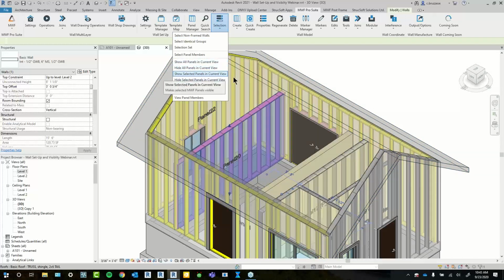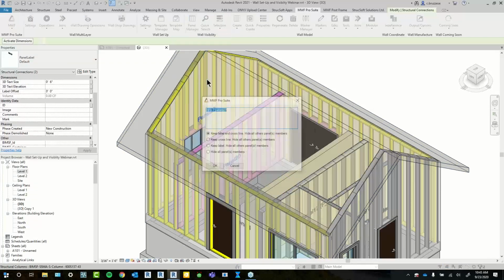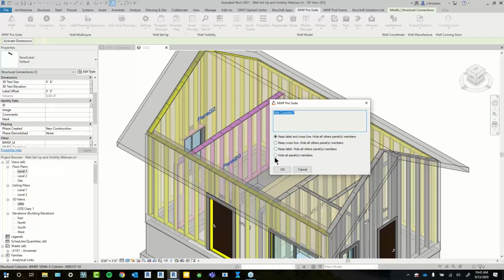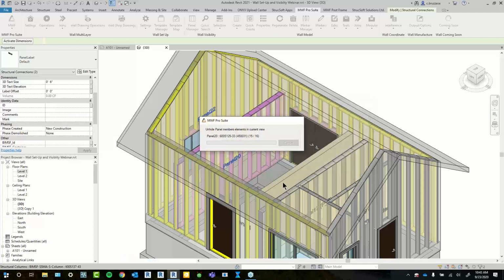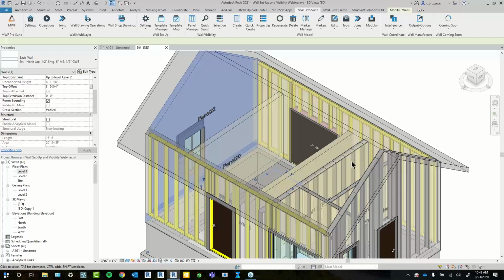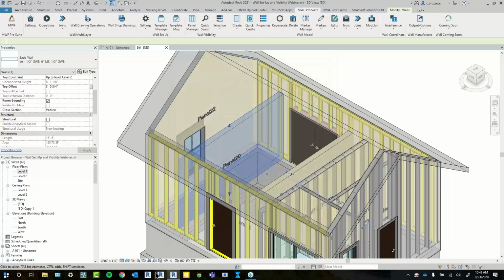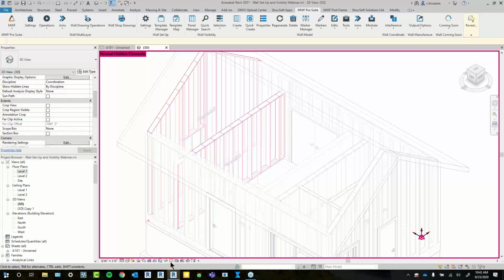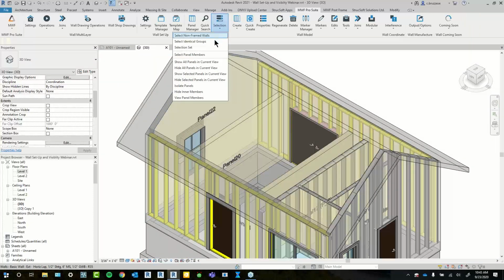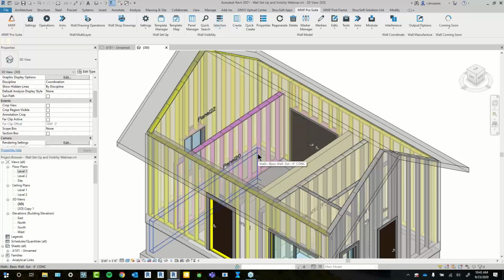And the last two commands on this is just for selected panels. With the selection, what I do like is that if ever you do want to maybe just keep the label, but hide the members, again, maybe just for a layout, then it will at least let you keep those labels. Again, they're still active, but it'll just hide the steel for you temporarily. And then you could, of course, force them back and show the members.